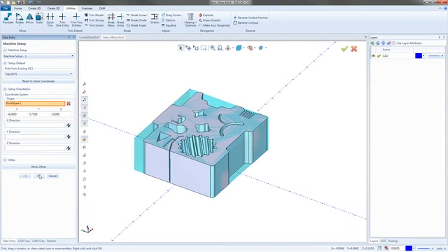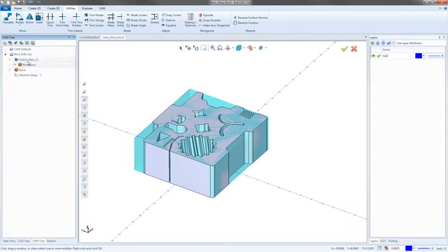And then when I'm all done, I'm just going to go ahead and hit OK. Now, I did not pick a workpiece. You really don't have to. When you're only working with one solid, you really don't need to change the workpiece at all. If you have more than one solid, that's where you'd want to start adding your workpieces in. Even if I have multiple solid models in my CAD window, if I turn my workpiece on and launch my simulation, the solid that pops up is the one that I selected. So if I had 5 and only picked one for the workpiece, then that one workpiece is what we have. So right here, we have our stock made.